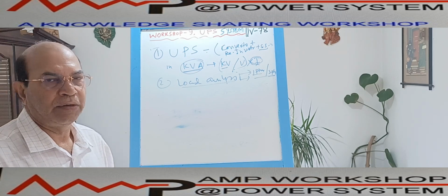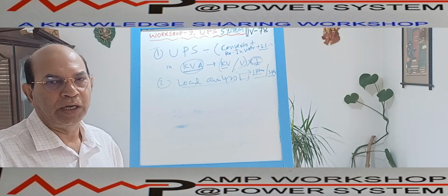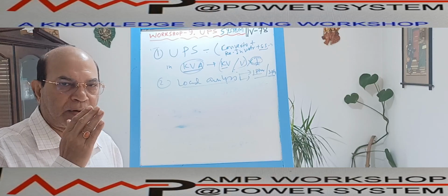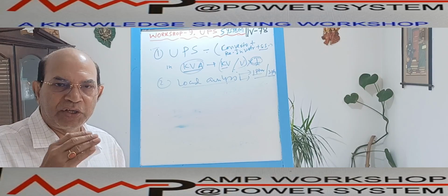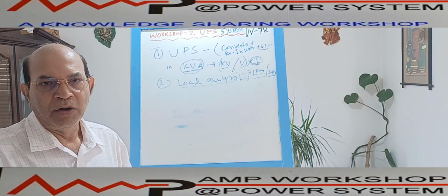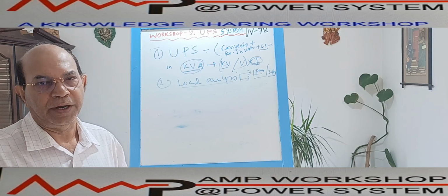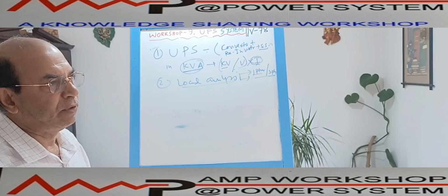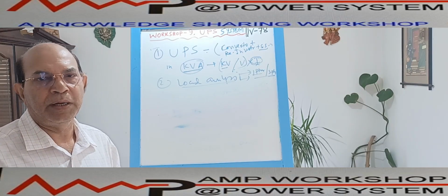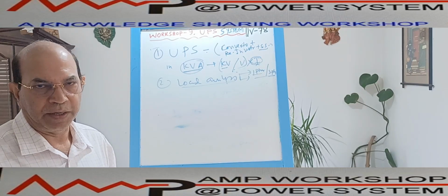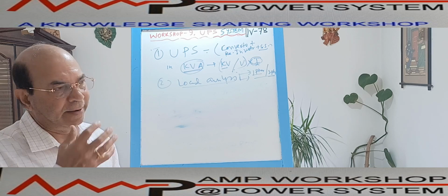Once the load is identified as single phase or three phase, we have to look into whether this particular load takes a constant current continuously from the start to the end, or takes a variable current, or has some inrush current. That also we need to identify. Sometimes some loads do not give their rating as voltage and current. They may give it directly in VA, volt ampere. Then our job will be very simple. We will record that volt ampere and the voltage.